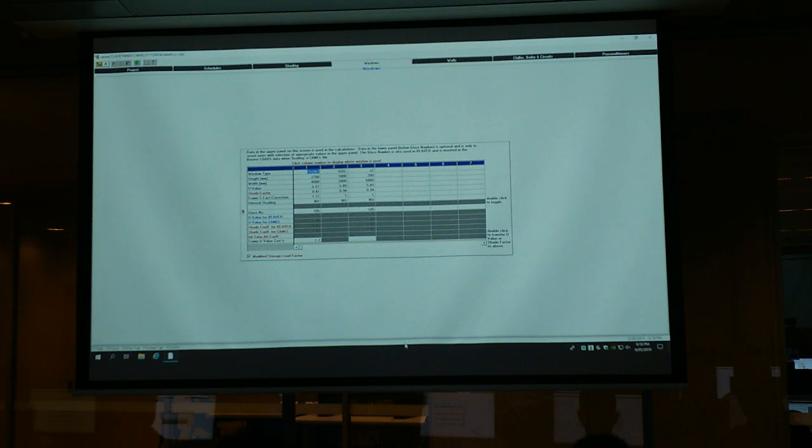Not the location yet. Then on the wall side you will locate where the window should be. But this part you just define the size of the window. Okay, like window front, 2,700 millimeters high, and the width is 4,000 millimeters. And then the U value depends on the window, okay?